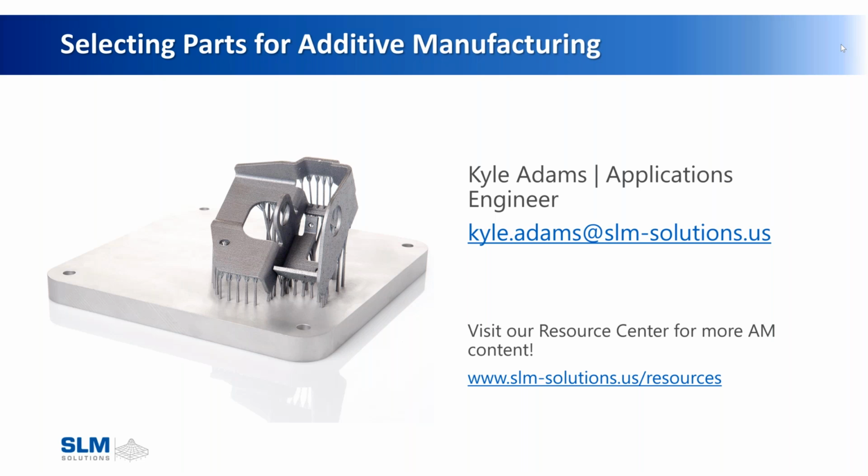Yeah, and also with FDM, especially FDM metals, you have limitations on thicknesses, actual wall thicknesses and volume thicknesses, whereas with powder bed metal, and that's because there's binder inside there that needs to be baked out. So if you say you have a 3-inch cube with FDM, you're not going to be able to bake the binder out of that. But with metal powder bed, there's no binder to be baked out. So you can weld a 3-inch cube no problem, and you can weld any geometry you want no problem, because there's no post-baking process that's needed to create the solid metal afterwards.